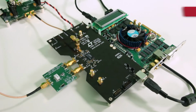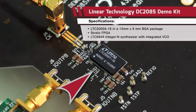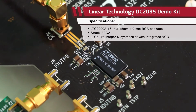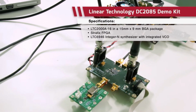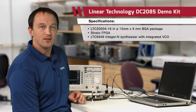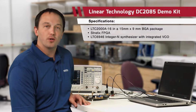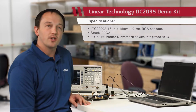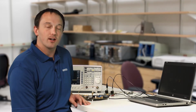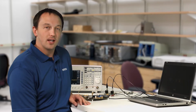Today we have Linear Technology's DC2085 demo kit to show you some of these capabilities. On the board we have the LTC2000A-16, which is the 16-bit version and comes in a 15x9mm VGA package. There's also a Stratix FPGA, which is used to drive the 32-lane DDR LVDS interface. For timing, we have the LTC6946 ultra-low noise integer-N synthesizer with integrated VCO, and that's used to generate the maximum sample clock of 2.7 GHz, and it's also the recommended timing solution for the LTC2000A.